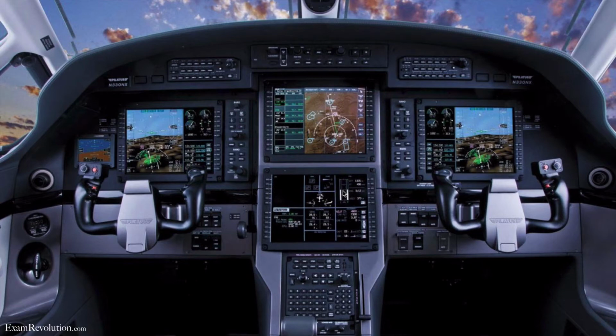Now what happens is, compression mode is when you lose this screen, for instance, or let's say you lose both of these screens, right? Both the MFDs are for some other reason gone, right? What it can do is, it can take this PFD and it can go into compression mode. So instead of showing you the engine parameters there like it is, and all the radios over there, it will take some of this information and show it on here. So it will throw away some of the radio information and some of the engine information, and it will show you some of the systems information on this screen over here.